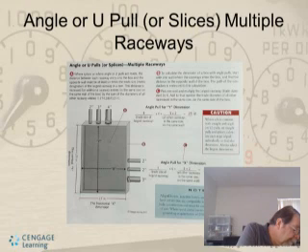This distance is increased for additional raceway entries in the same row on the same wall of the box by the sum of the dimensions of all other raceways. This is designated in 314.28(A)(2).